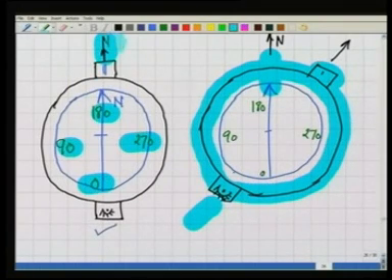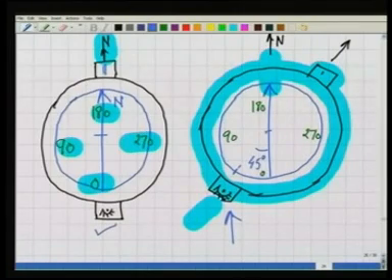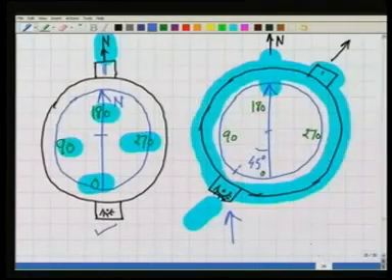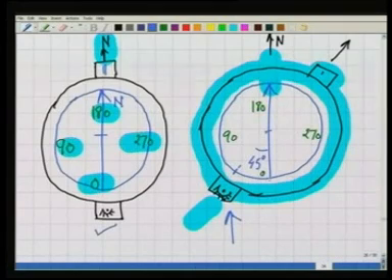Now at this moment, if I look through the prism, which is kept here, it will read the graduated circle here. So the reading in this case will be, as you can see, around 45 degrees. Of course, the graduations I have written here look erect, but they are not erect, they are inverted. Only this prism will erect them. So our bearing, as you can see here, is around 45 degrees, and this is what we are observing over here. So this is how we can take observations with the prismatic compass.